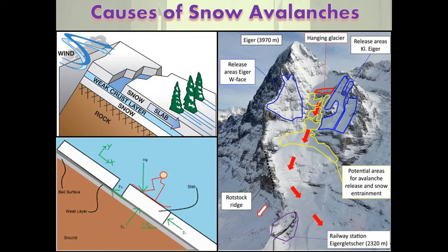Snow does not accumulate significantly on steep slopes. Also, snow does not flow easily on flat slopes. Most avalanches of dangerous size therefore originate on slopes with an inclination between 30° and 45°. On slopes from 45° to 50°, sluffs and small avalanches are common, but snow seldom accumulates to sufficient depth to generate large snow slides. Convex slopes are more susceptible to avalanches than concave slopes.